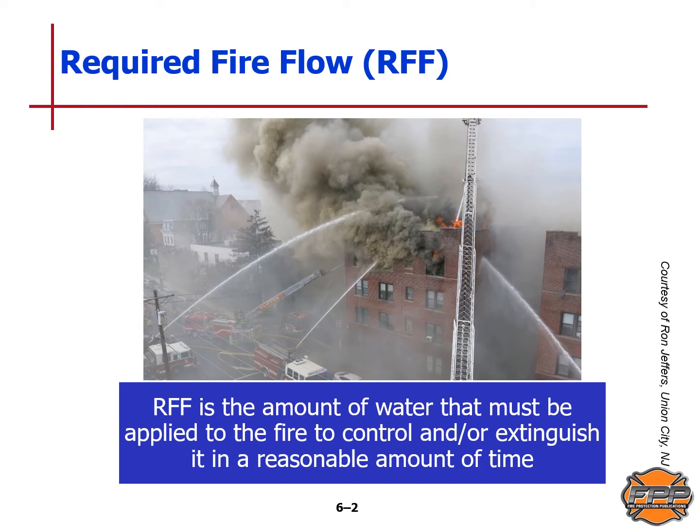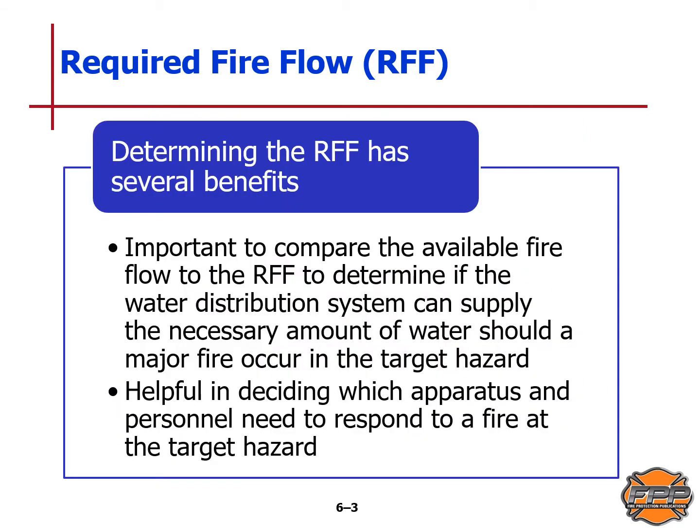RFF is the amount of water that must be applied to the fire to control and/or extinguish it in a reasonable amount of time. Determining the RFF has several benefits. It is important to compare the available fire flow to the RFF to determine if the water distribution system can supply the necessary amount of water should a major fire occur in the target hazard. It is also helpful in deciding which apparatus and personnel need to respond to a fire at the target hazard.